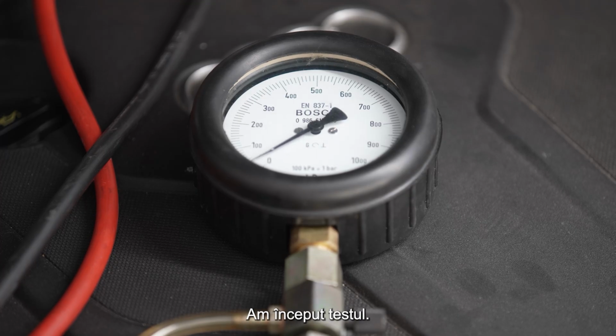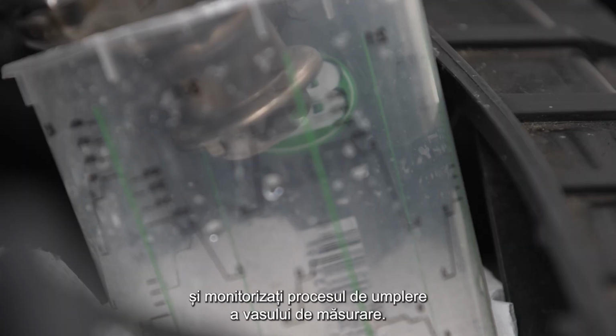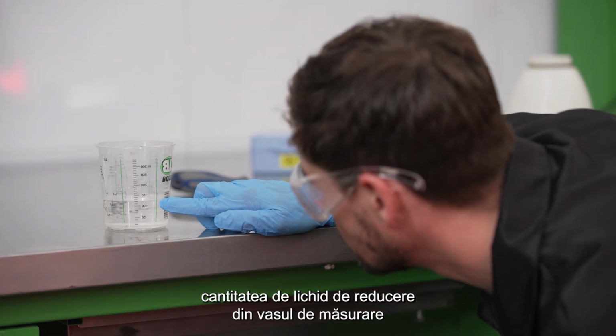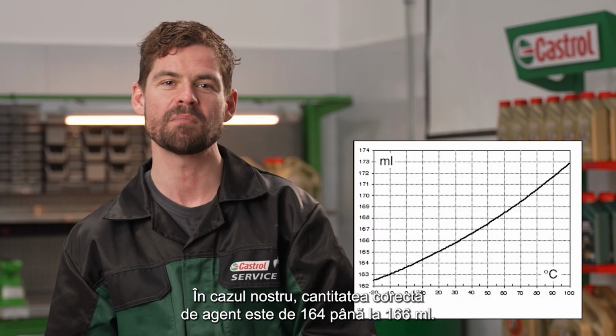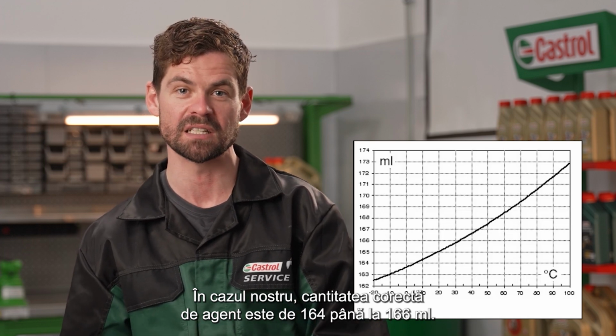Alright, so we've started the test. Now take a close look at the pressure gauge readings and monitor the filling process of the measuring vessel. After the test, we need to check the amount of liquid of the reducing agent in the measuring vessel and compare it with the reference value displayed on the computer. In our case, the correct amount of agent is 164 to 166 millilitres.